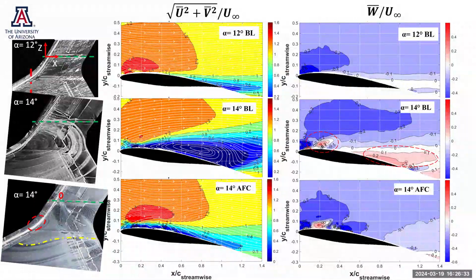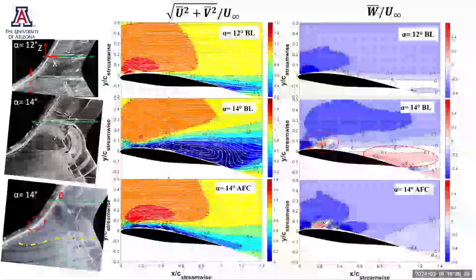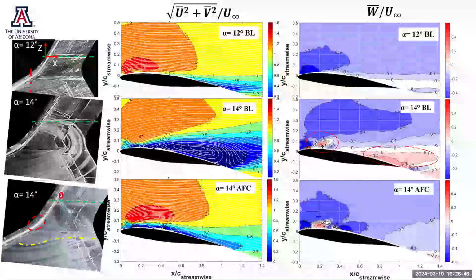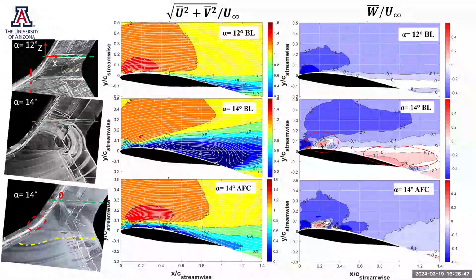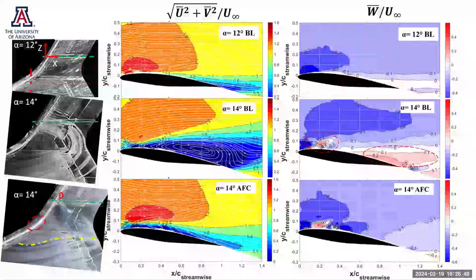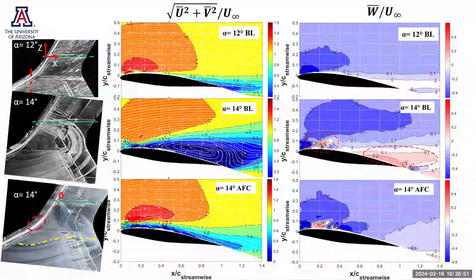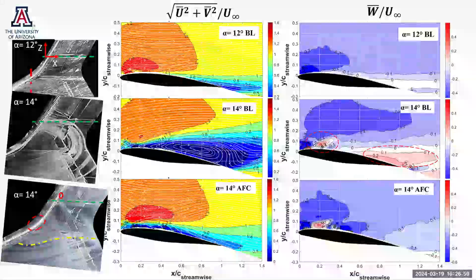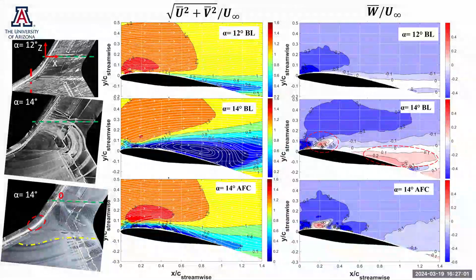From the oil flow, you can see that the actuator is located here, and the jet comes out in this direction. The PIV laser plane is here. The jet is highlighted here in the dark blue region. There are tiny recirculating regions of the jet, identified by this tiny red region. And then we have the leading edge vortex for the outer wing.